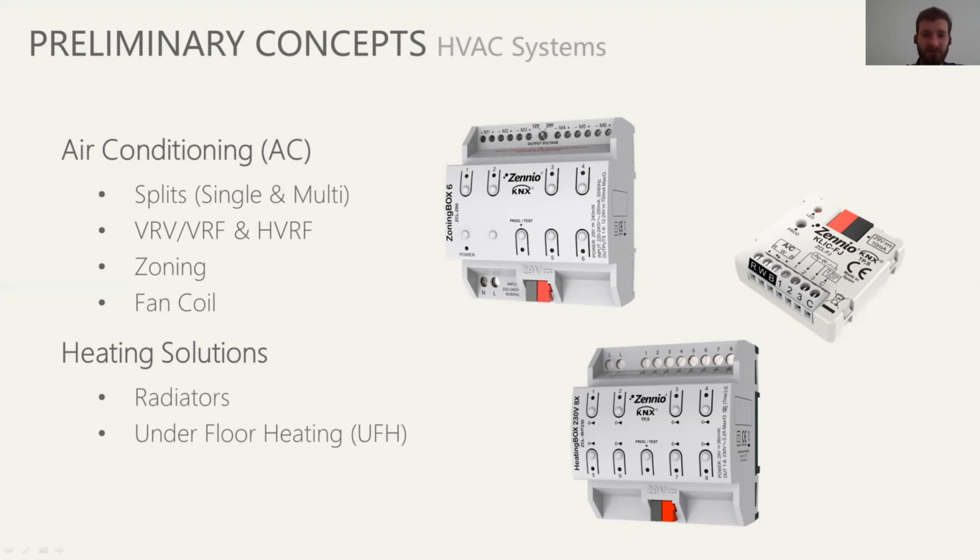I'm not trying to go into a depth explanation of each of the systems in HVAC, just trying to mention some particularities of them. So the main difference between radiators and underfloor heating is that radiators work on the principle that they produce a very big temperature difference, while underfloor heating works on a very low temperature difference.